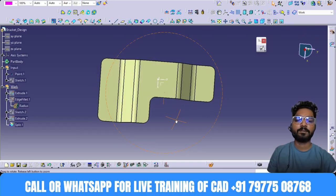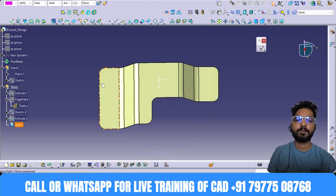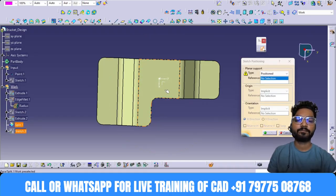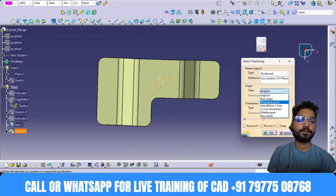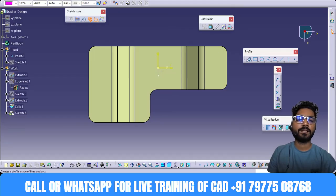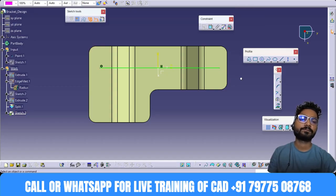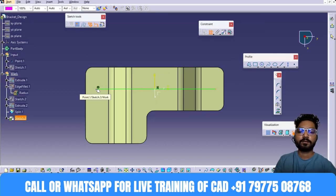Now on this bracket shape, I want to add one mating flange. For the mating flange I'll take one more sketch here. Select this plane, then the projection point is this one, and click OK. For the mating flange I'll create one line like this. This dimension will give 340. After applying the dimension, exit.